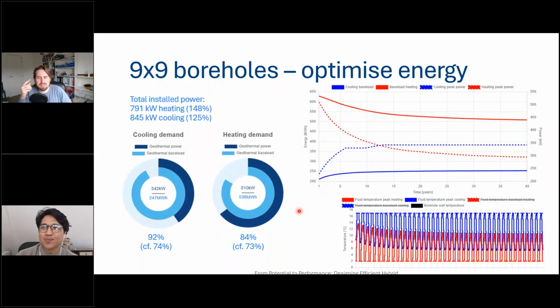You can of course make a system as complicated as you want as a designer, but in the end, it's not so much about costs as about the risk that something is wrong with the surface installation because a valve is set in the wrong direction. That's real. When it comes to hybrid designs, I do not have a special slide for that, but you can come up with hydraulic configurations and control strategies which are really simple and just temperature based.